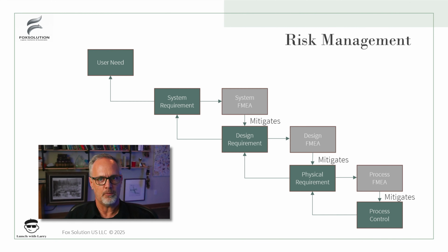And then finally, the process failure analysis takes those physical requirements, like the 3/8 inch bag seal, and defines all the ways that that bag seal wouldn't be delivered. So you get a hair in the seal, which creates a tunnel, or we have delamination of the bag. Those different problems are associated with the manufacturing process, cleanliness of the process, or maybe how the sealing's done, the pressure of the seal, the temperature of the seal. And then what ends up happening is we have a set of process controls that are necessary to assure that we get that 3/8 inch bag seal.